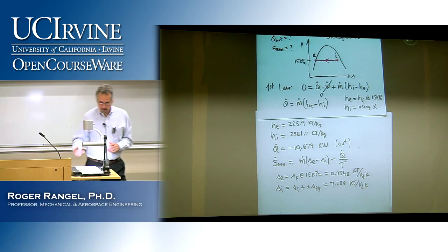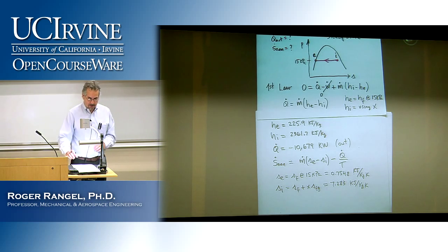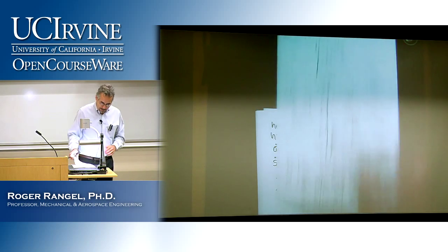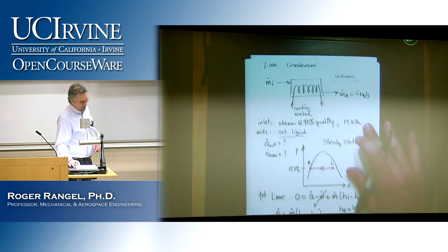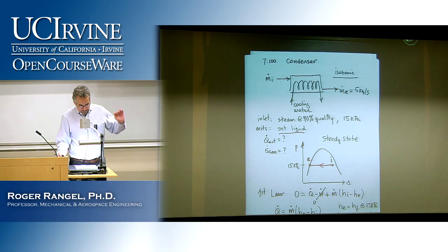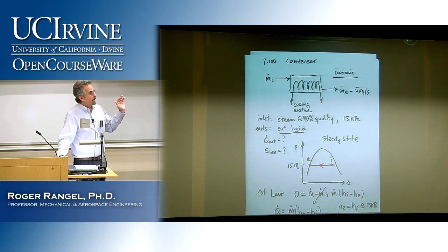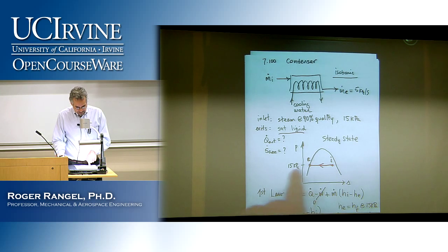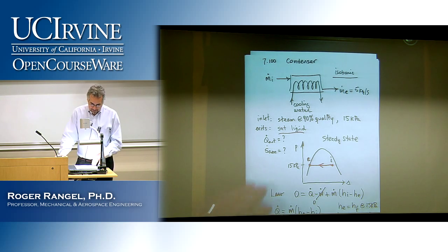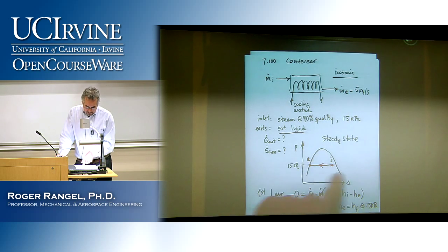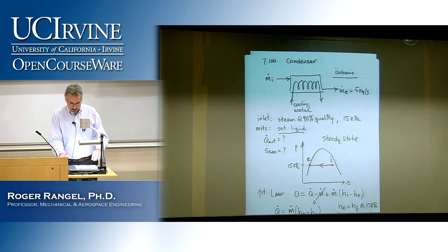Think about this problem for a second, and we'll have a little bit of a discussion about this temperature. If you go back to the sketch, and even our diagram here, the condensing water is very easy because it's at a constant temperature. It's just turning the vapor into liquid, all happening at the same temperature because it's at a constant pressure inside the dome.